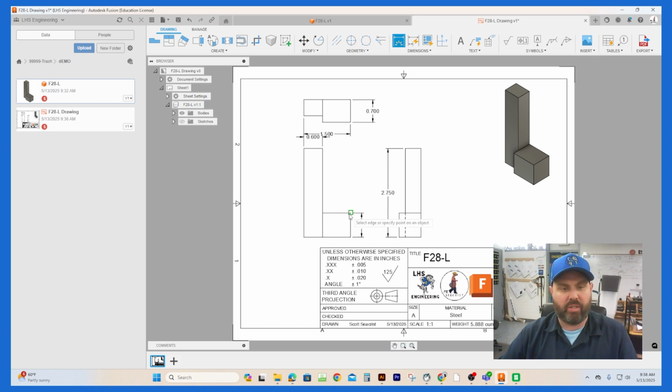How far is it from here to here? Once again, it doesn't say, but we can use math, subtracting 1.5 from 0.6, or correctly, 0.6 from 1.5, telling us this is 0.9. So we don't need to put a number there. From here to here, it says it's 0.75. From here to here, it says it's 1.5 right there. Notice I'm only working with inside and outside corners. I didn't stop at the midpoint.